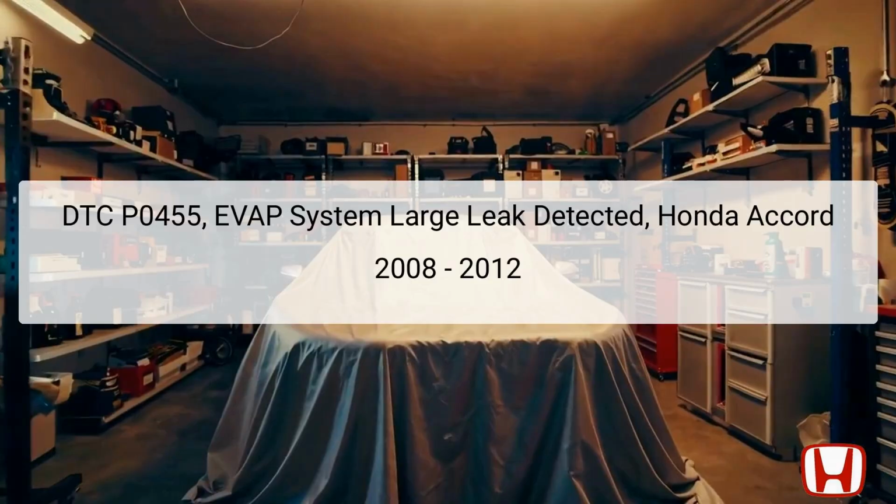Diagnostic Trouble Code, DTC P0455, indicates a large leak detected in the Evaporative Emission Control (EVAP) system of the 2008 to 2012 Honda Accord. The EVAP system is crucial for trapping fuel vapors from the fuel tank, preventing them from escaping into the atmosphere. It consists of components like the fuel tank, fuel lines, vapor canister, and valves, all working together to maintain emission standards.